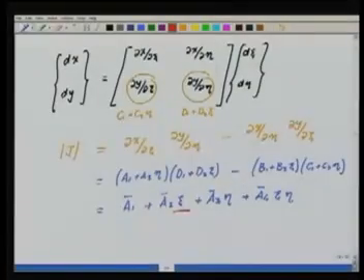Even with this bilinear map, the Jacobian is no longer a constant because it is now a function of psi, eta and the product psi eta. While in the triangular element, when we did the linear map, which we had discussed, the Jacobian turned out to be a constant. So when I am going to do the numerical integration and so on, I have to account for this part of the Jacobian.